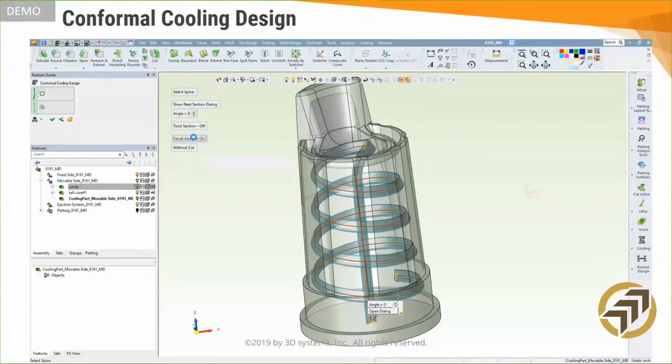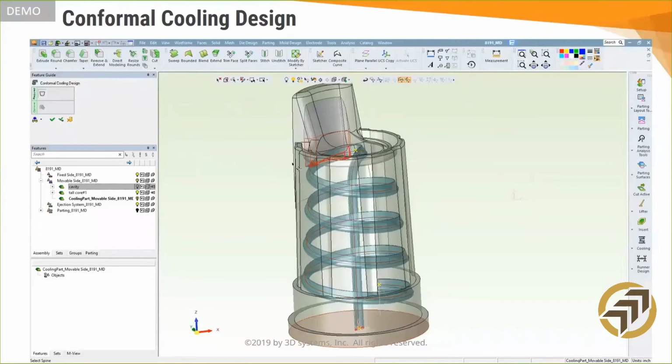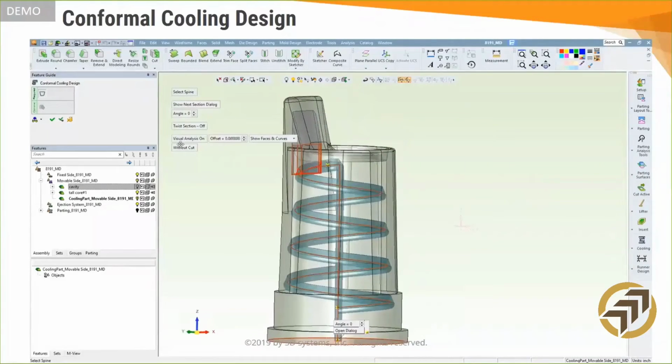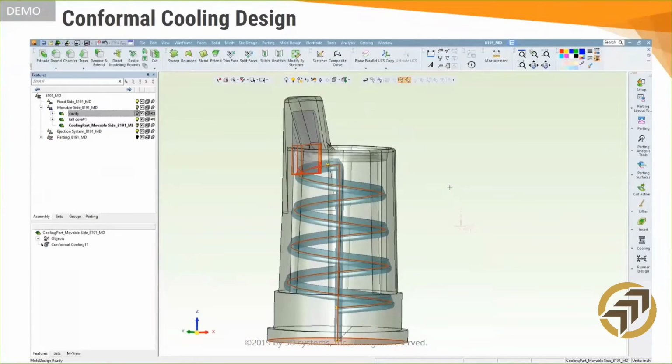At any junction point along the curves, the shape can be changed to another so that perhaps the ins and outs can still be round for standard components or for mating up to other water lines. And another built-in feature of conformal cooling is collision checking. With or without an added safety offset, the new cooling channel can check for contact with existing features like pockets or ejector pinholes.